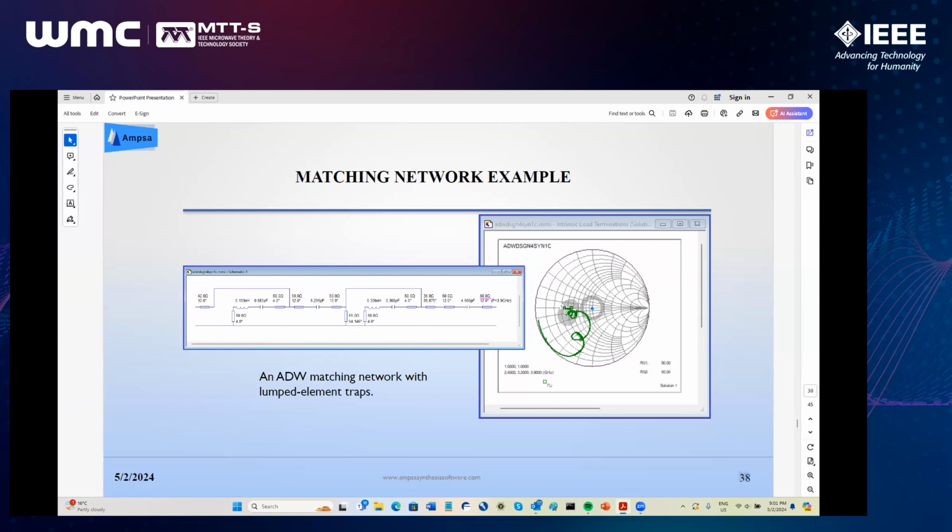It's running around there in the middle. And then it's going like so. Now you can see this is not far from class B. Now this is a terrible bandwidth. This is 1 gig to 3.9 gig, very wide. Effectively, in some parts, you cannot control the harmonics because the second harmonic is also the fundamental and the third harmonic is also the fundamental. So you simply cannot control it there. But the software understands that, so you can set it up for that.